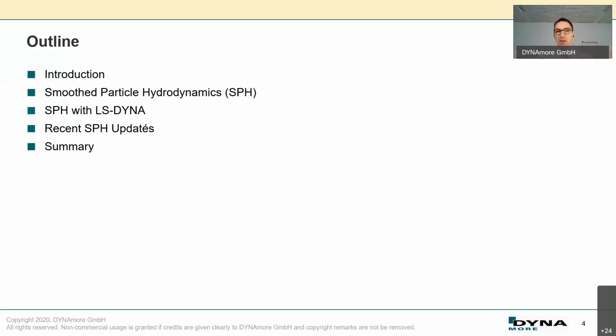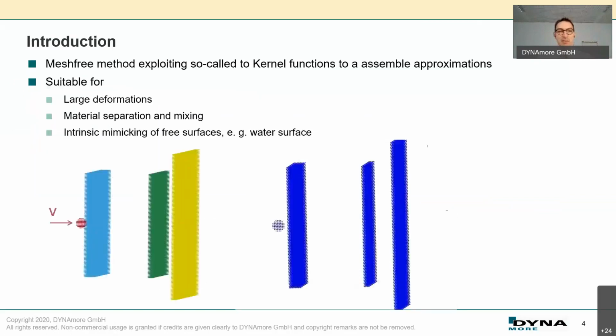So what is not the finite element method, but what is the SPH method? In general, SPH is a mesh-free method. I don't want to call it a particle method, because although it may look like one, we prefer to call it a mesh-free method. It's still based on continuum mechanical equations, but not using a fixed mesh like the finite element method. Instead it has particles, and these particles serve as computational points. So what is the benefit in comparison to the finite element method, for instance?